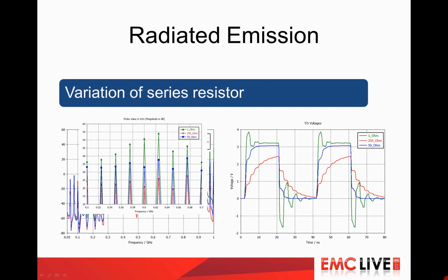In the second part, I was showing you the workflow for a coupled simulation of emission from a PCB, where we use the 3D solver to analyze the structure and the circuit simulation to obtain the results we are interested in. And due to the high integration level of CST products, the circuit simulation allows you to also calculate field values, with a feature which is named combine results inside the CST Studio Suite. And in the last section, I was showing you two examples on a realistic PCB, showing how conducted and radiated emission can be simulated.